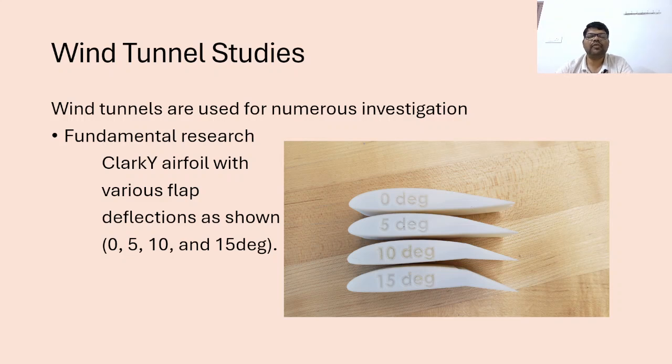The second, third, and fourth aerofoils have flap angles of 5, 10, and 15 degrees respectively. These aerofoil models with different flap angles are kept in the test section of the wind tunnel to understand the flow behavior and to measure the forces like lift and drag, and the effect of the flap angles on the forces exerted by the flow. The aerofoil you are looking at in this image is the Clark Y aerofoil. This is one of the examples of fundamental research.